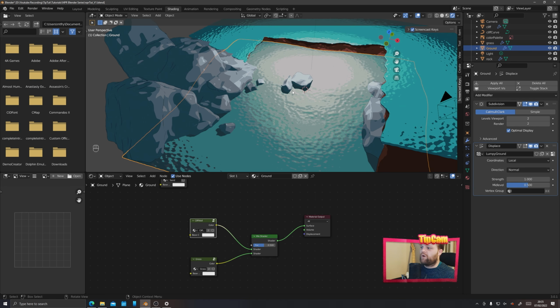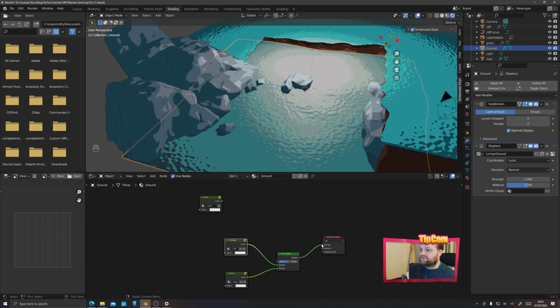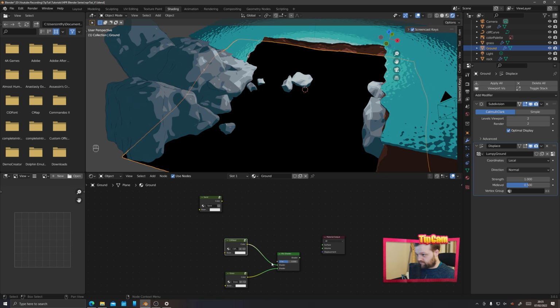Not exactly what we want. What we want is this factor, what is visible from material 1 and what is visible from material 2, to be a mask. We want to choose the area in which it is masking. So what we'll do is we'll disconnect this from the surface, first of all. And we'll disconnect these from the shader as well.